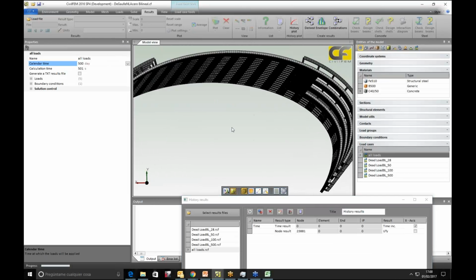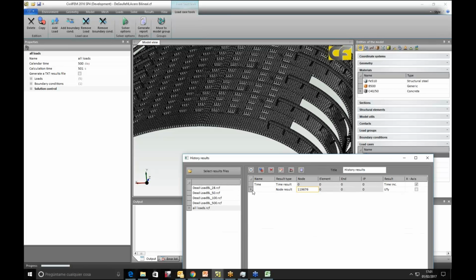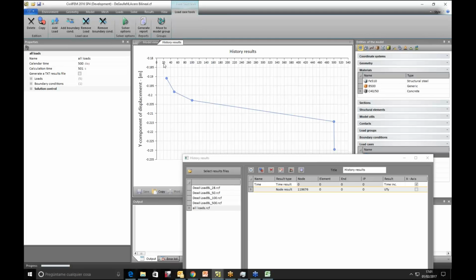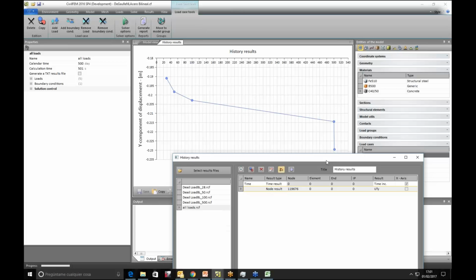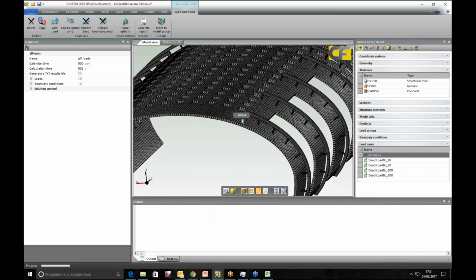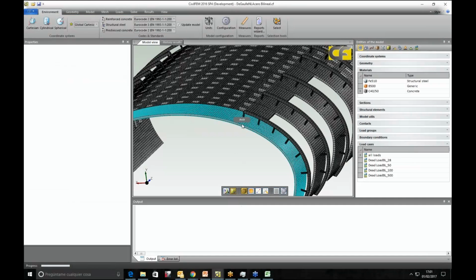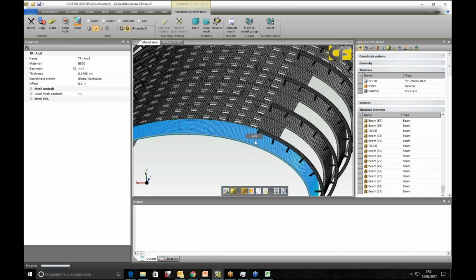Let's see the midpoint where to plot them. The node in this case is 119,676. Now we are plotting vertical displacements. We can see these vertical displacements are generating a curve similar to the previous one we got, but when applying thermal loads, we also have a vertical displacement. In this case, we didn't cancel or deactivate any part of the model as we did before. We just modeled it with the real nonlinear concrete behavior, cracking and crushing, so these elements have cracked and crushed, and the deformed shape has increased.